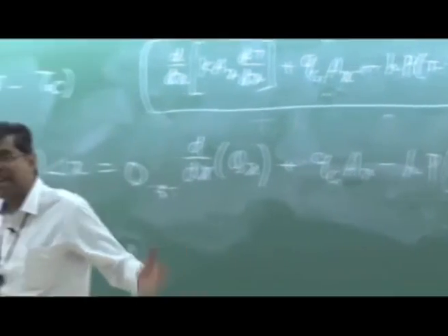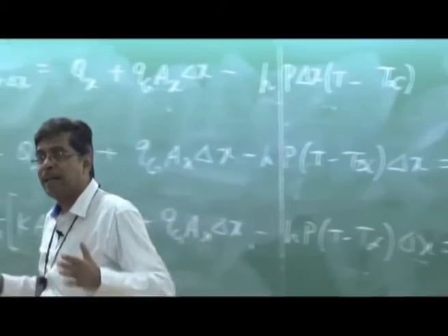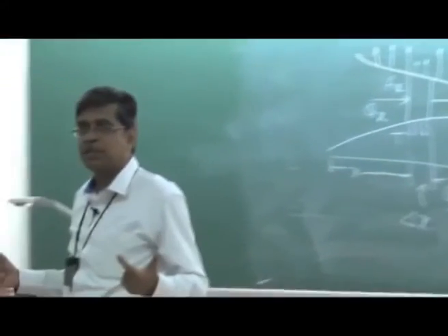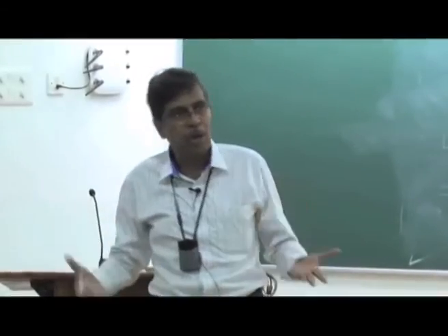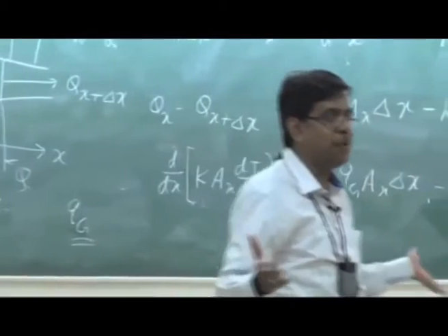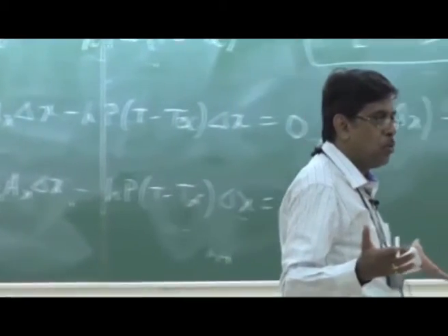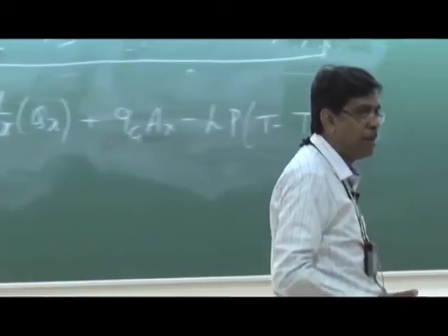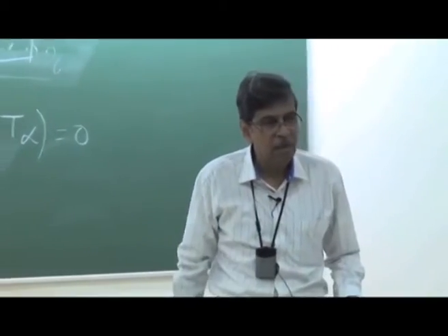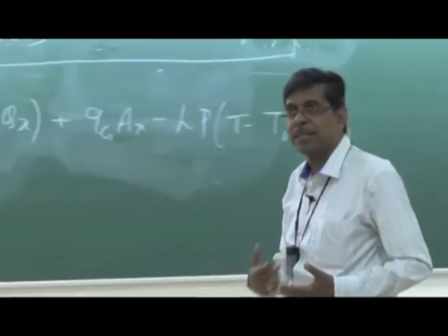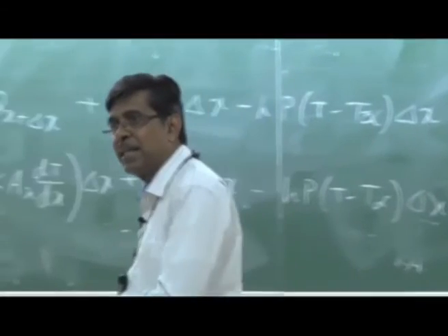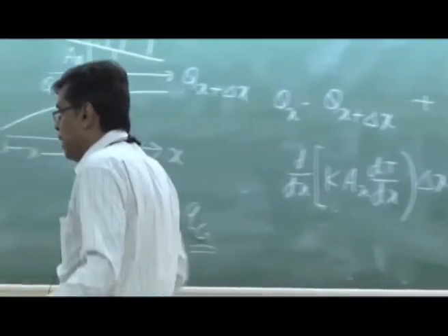You can get a generalized expression for heat transfer rate and temperature distribution in any steady one-dimensional flow with or without thermal energy generation, with or without convection from the lateral surface. So fin is one application of the one-dimensional steady-state heat conduction problem, that extended surface, where one-dimensional heat conduction is associated with lateral convection, and this is taken care of in the simple energy balance.